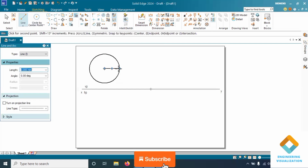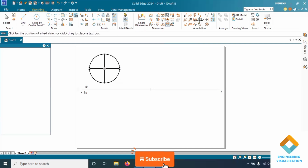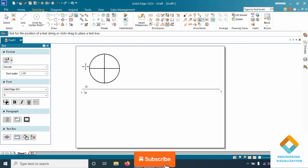Here I'll construct a circle using the center method. The diameter will be taken directly as the major axis dimension. In the question the major axis is 60 mm, so we'll take the same diameter, that is 60. Enter. Now we need to divide this circle into 4 equal parts.